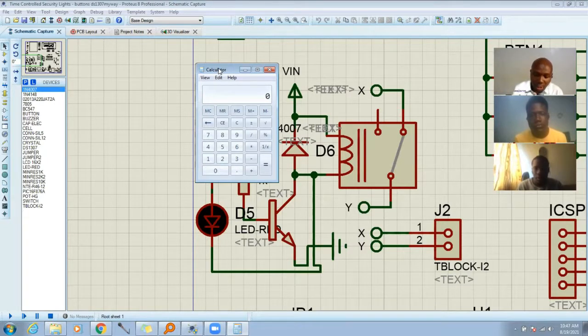Now, I told you this system can stand 2.4 kVA worth of load. That's what you can power at maximum. And the question is, if you have 100 watts of bulbs, how many bulbs will you have on the relay?